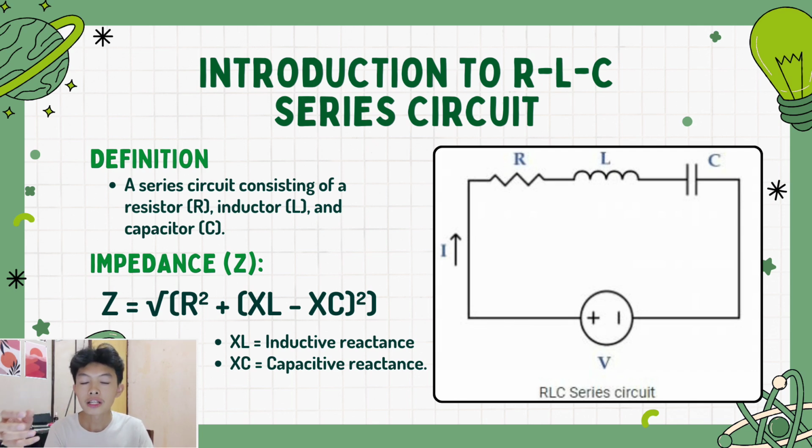So the total resistance to electricity in this circuit is what we call the impedance, denoted as Z. So we find it using the formula Z equals the square root of R squared plus the square of the difference of XL and XC, where XL is the inductor's resistance and XC is the capacitor's resistance.